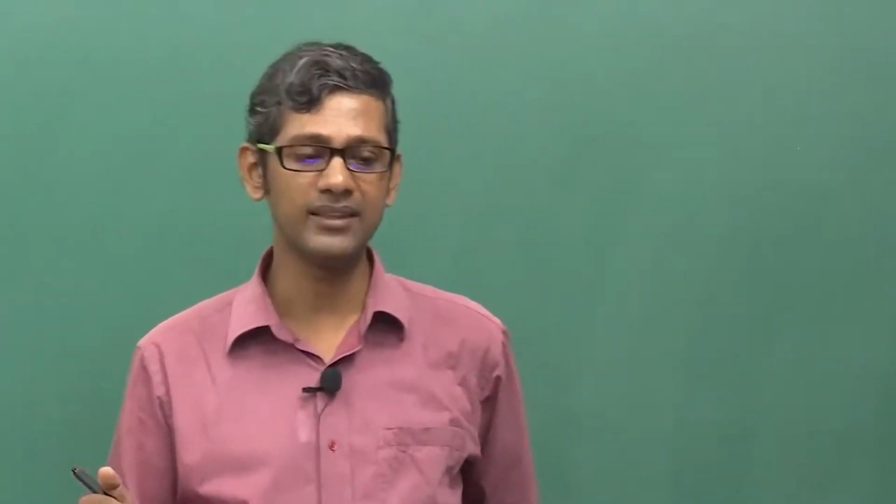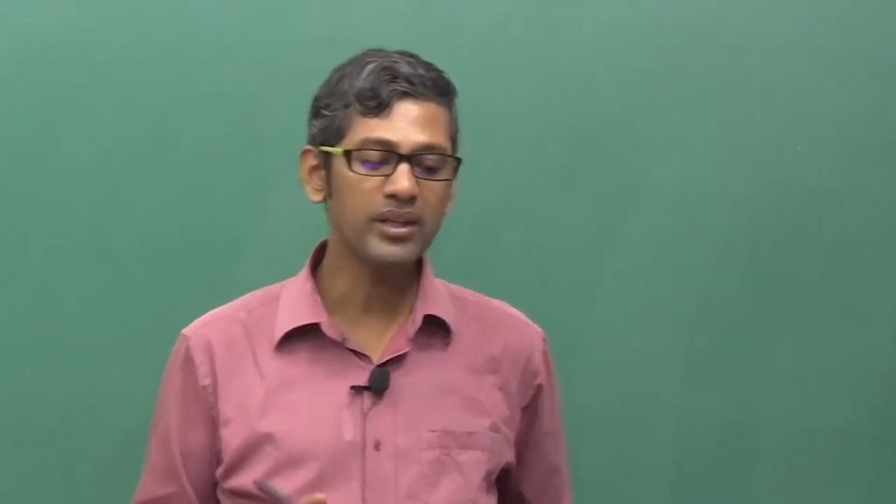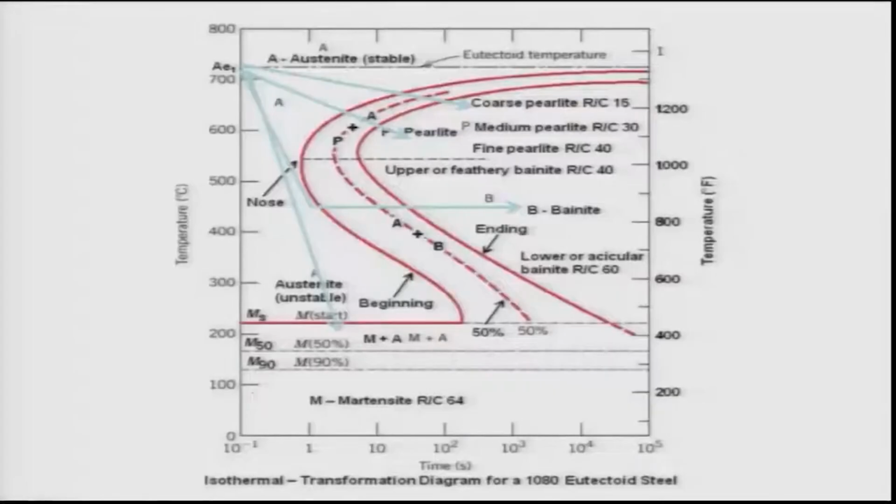Another feature is that, for martensitic transformation, the important thing is the critical cooling rate, known as CCR in the literature. The critical cooling rate has to be sufficiently low to be achievable. If it is very high, it cannot be achieved even by quenching in water.